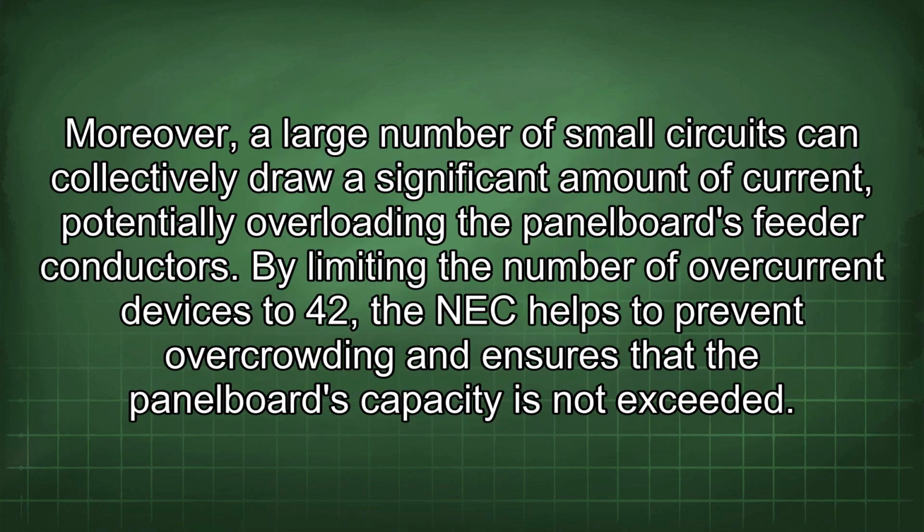Moreover, a large number of small circuits can collectively draw a significant amount of current, potentially overloading the panel board's feeder conductors. By limiting the number of overcurrent devices to 42, the NEC helps to prevent overcrowding and ensures that the panel board's capacity is not exceeded.